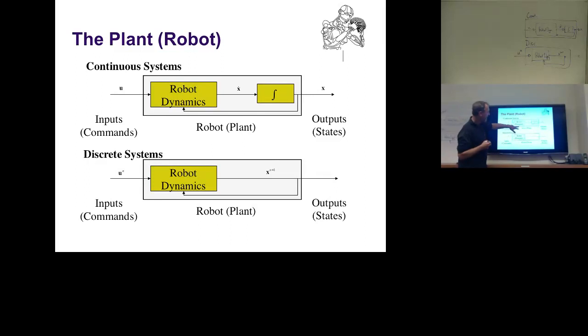So discrete systems omit the dot variable by directly going from where I am currently to where I am at delta t in the future. So there's always inherently some kind of a delta t time step. Very important. If you change the delta t, make it very big, the dynamics of the system change, and also the stability properties. Make it very small, they will be different in a particular way as well. Okay, so this is the intuition.